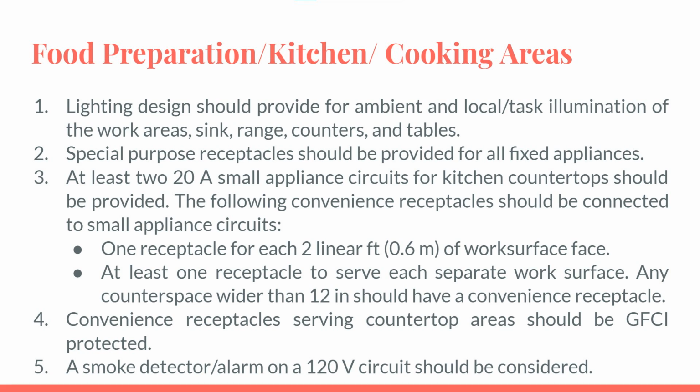Third, at least two 20-ampere small appliance circuits for kitchen countertops should be provided. These circuits are in addition to those required for refrigerators, ranges, microwaves, lighting, and so forth. Outlets on these circuits should serve only the kitchen, pantry, and/or dining room areas.